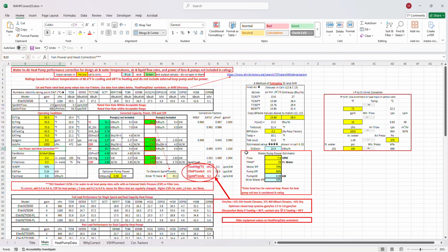And then you can see that did the trick there. It got us down to 102, and CFM per ton is 372, which is pretty nice. And you see, it dropped that SHR down to 0.74. Now maybe we need to reduce the water flow a little bit. So let's try 8 GPM. And when we do that, what we have to do is take this number and type it. You can't cut and paste. You can just type that number 32.1 into that cell, and you can see we're down around 3, which is a pretty good number.